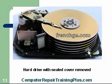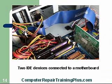Here you see an IDE cable, a 40-pin cable, being connected to a hard drive and to a CD-ROM. Now, a lot of these cables are 80-pin cables. They look pretty much the same. You still have 40-pin connectors, but they allow the data to be driven a little bit faster. There's only 1 connection on the motherboard here. A lot of motherboards have 2 connections so that we can put 4 devices on the computer.